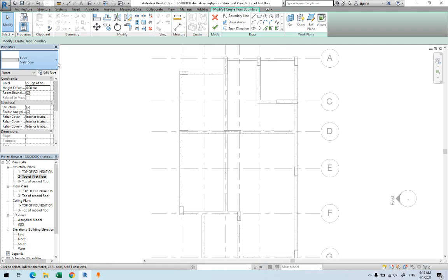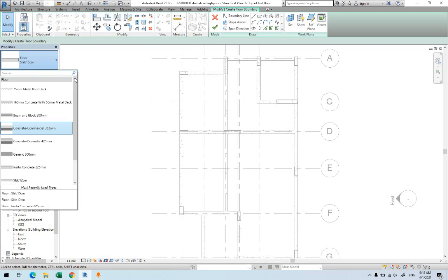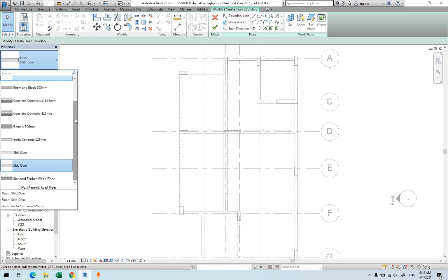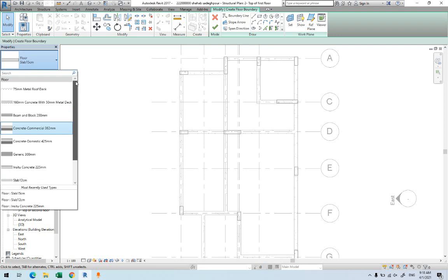Now, first thing, you have to select the type of the floor that you have. Now, I'm not going to go into detail of the layers. You already know from the wall that you can add multi-layers if you wanted. Here, the idea is to draw the layering, the materials. You can do it anytime. Now, if you don't see those in millimeter, most probably it's due to the template that you have. Here, you cannot load family that is already available within the template.